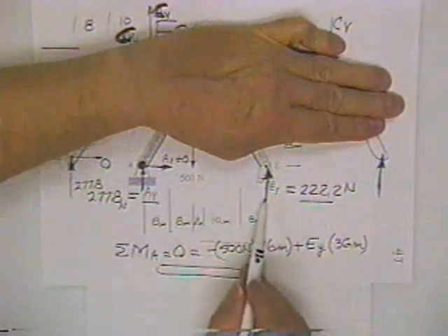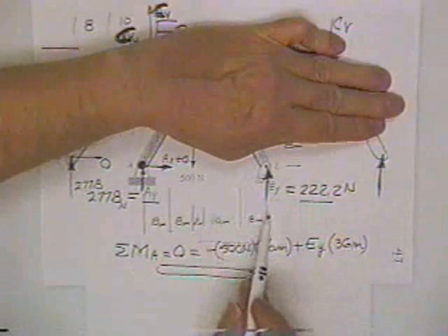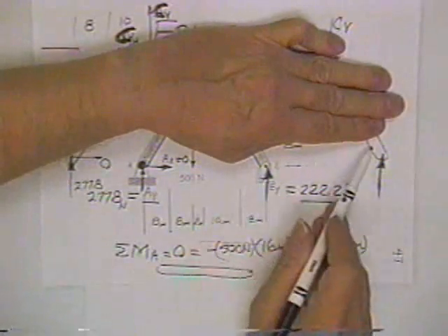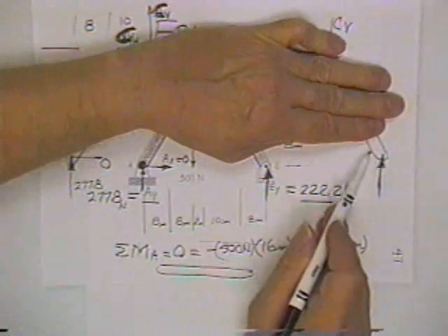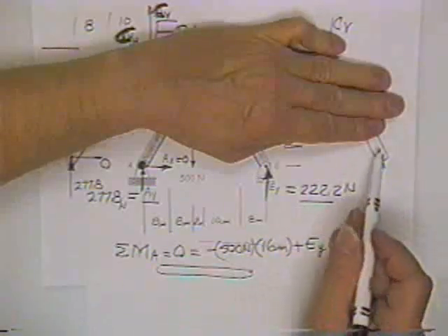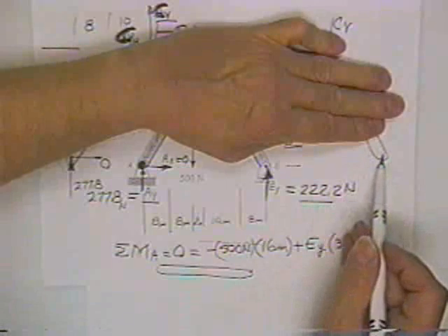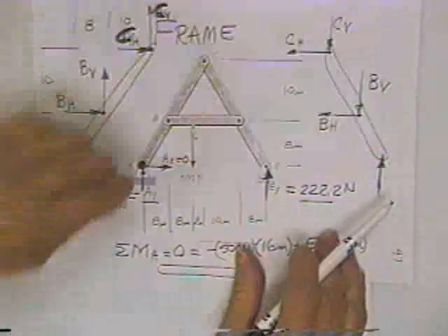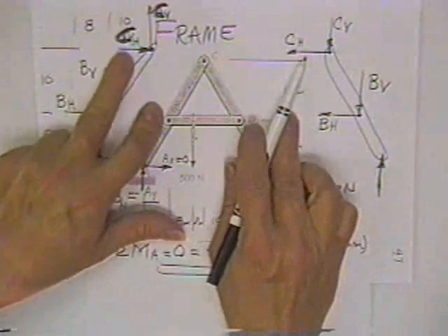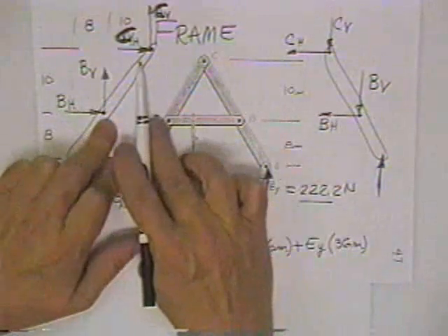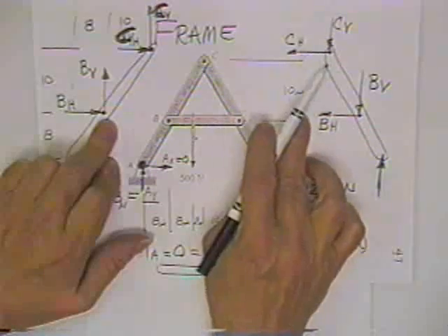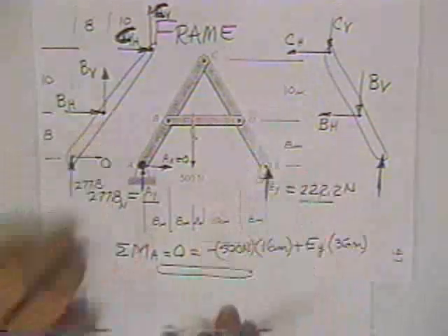In other words, if EY was guessed up, or even if it is proven to actually go up on this member, and you merely redraw the member like a ditto machine or like a Xerox, you wouldn't expect this arrowhead to flop on the Xerox. You just redrew the member, you redraw the force. Then why do these not match? The reason is because if this goes to the right on this member, it goes the other way on the other member.